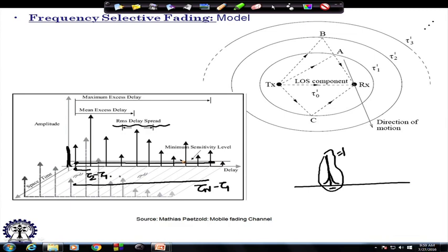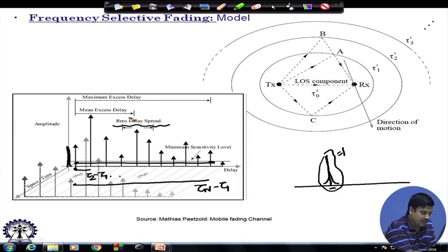So, to measure the spread, I would like to measure the delay, which was almost 0 in an impulse. Delay has now become spread out, that is why it is called delay spread. What is the root mean squared of the delay is what we need to measure. That is one of the important ways of describing such a profile. By a single parameter we can say that on an average what is the root mean square value of the spread that an impulse is getting. This is one way of describing it.